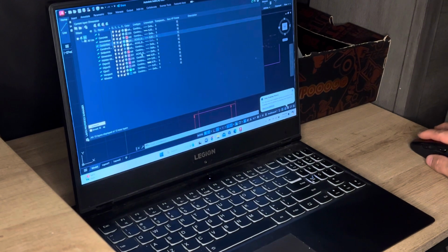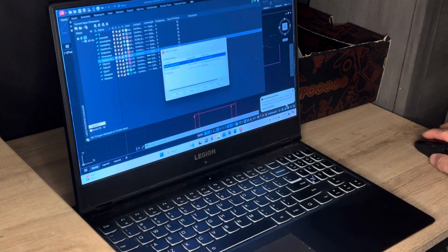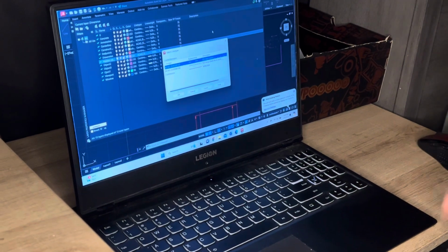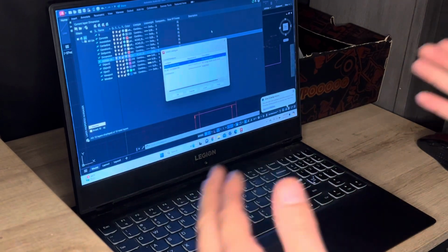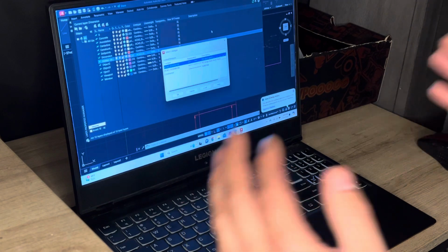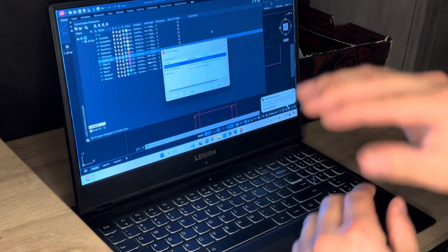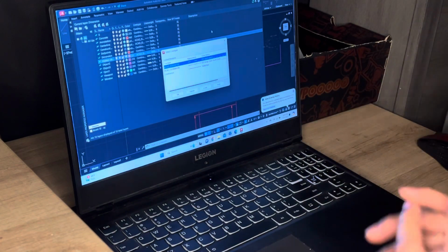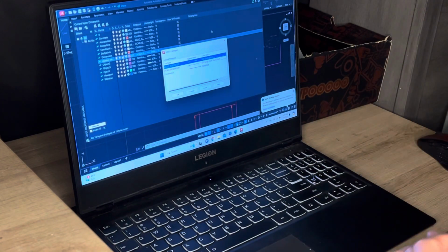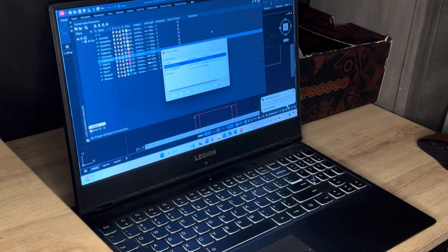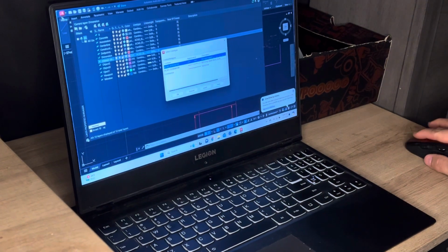And a hidden object is also a dashed line, and it's a light color, and I would use that if I'm focusing on the top of my deck with the joist, maybe I'm doing a dashed hidden line for the beam line under it, so that way you could still see where the beam is, but you also know that it's not the main focus of that drawing, right? It's maybe just there for forward thinking or layout purposes, right?